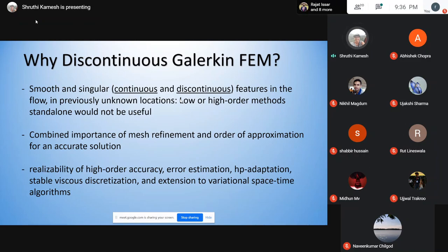And that's why you have discontinuous Galerkin, which is that when you're solving the equations, you solve for two values at the same interface, or two or three values, depending on how many connections there are or how many dimensions there are. So if six or seven elements are joined at a particular point, you would have six or seven separate values for those field variables, for those nodes.